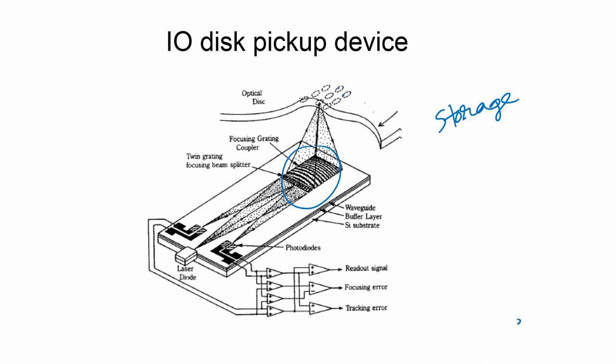The movement of the disc also could be arranged such that the bits are accurately aligned with where the spot is focused. For this arrangement, we start with the laser diode as the source of light, which is focused onto this grating. It could be directed by using other elements also if necessary. You can make another lens here.